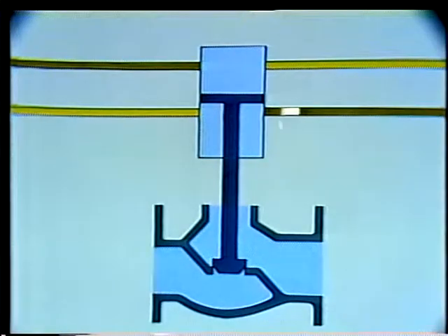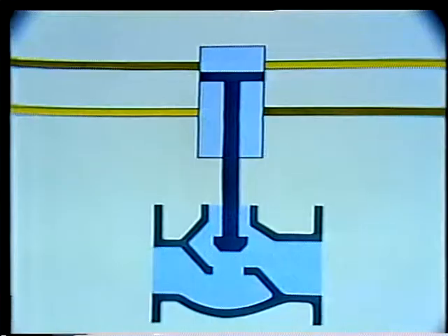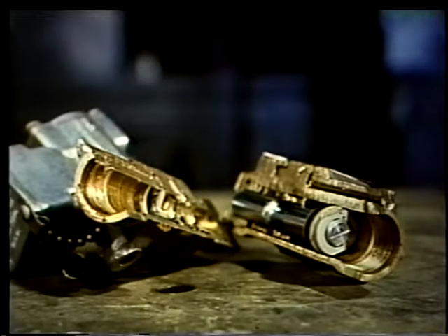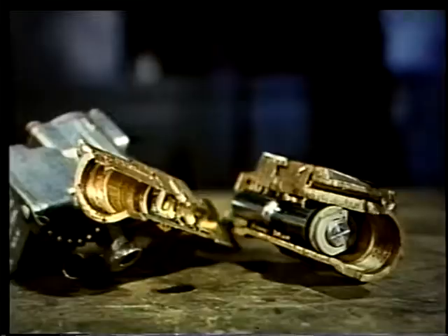If pressure is applied under the piston, the disc moves up, opening the valve. The top side of the piston is vented, allowing the piston and valve to make a complete stroke. The reverse takes place to shut the valve. Electric solenoid valves are usually used to control the flow of air to the valve. They are either fully opened or closed and are not used for throttling.